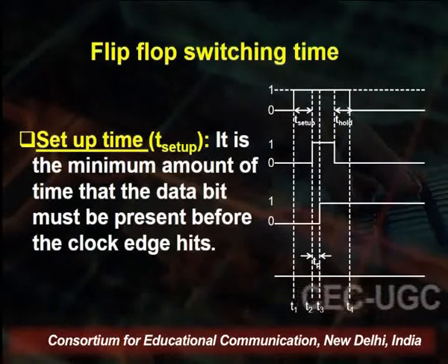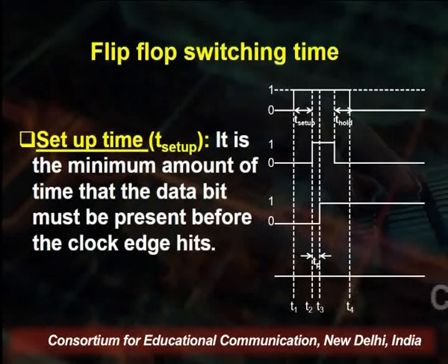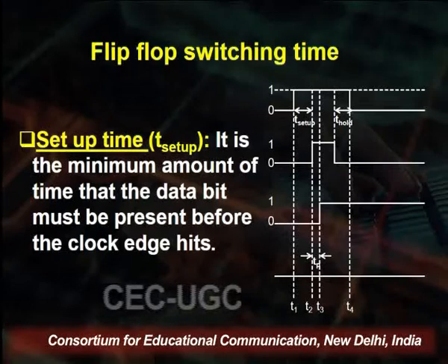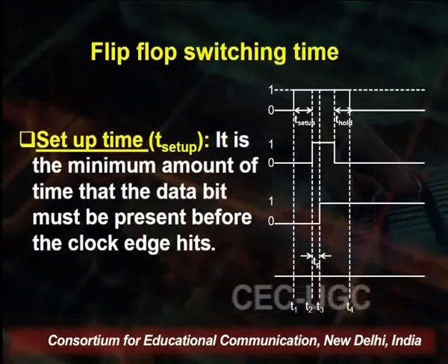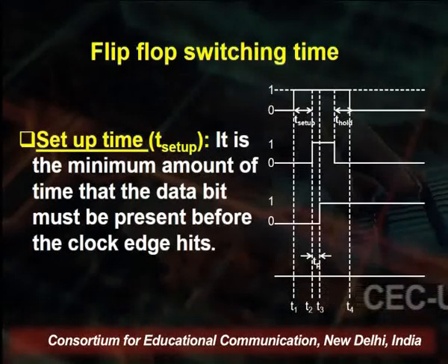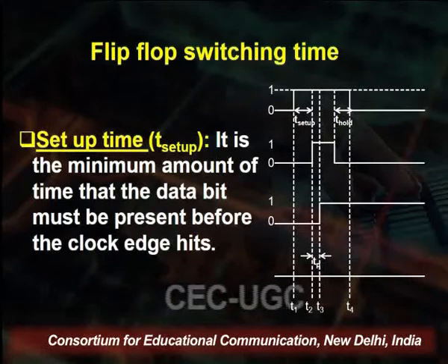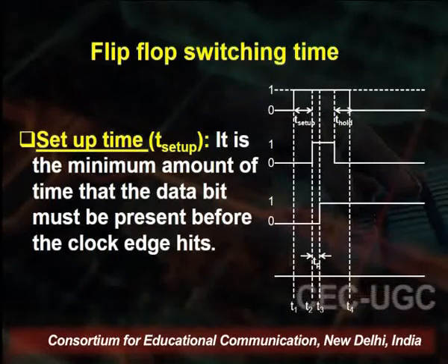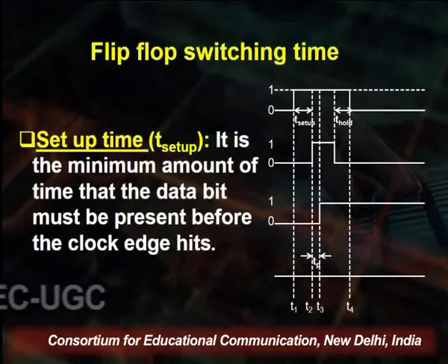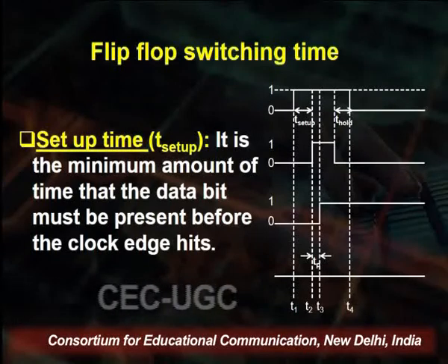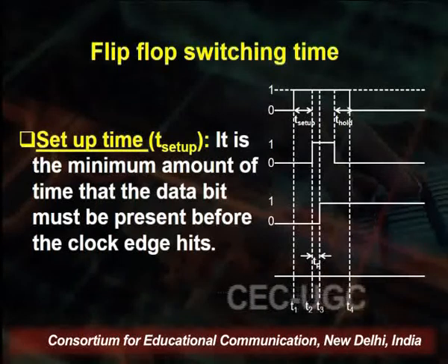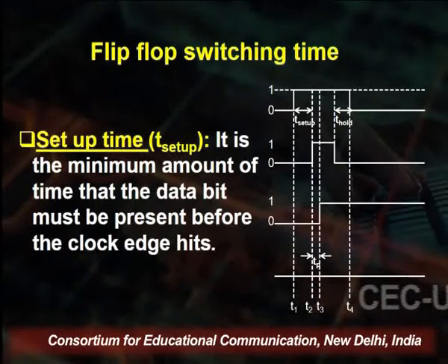So what is the setup time? Setup time means that the data at the input of the flip-flop should be stable or should be present before the clock edge comes and changes or helps transit the data from input to the output. In this case, from the D input to the Q output. That means data at the input should be stable before the clock edge hits.